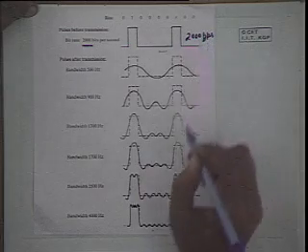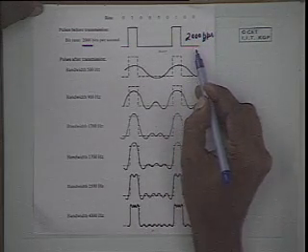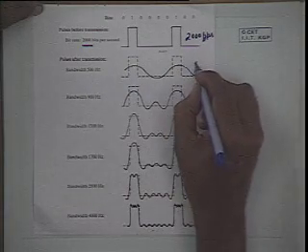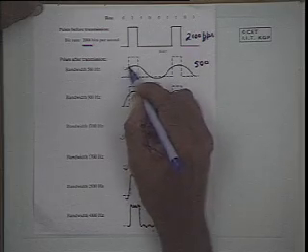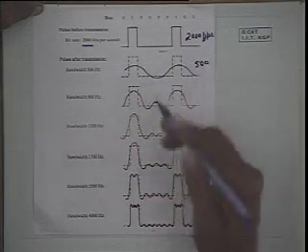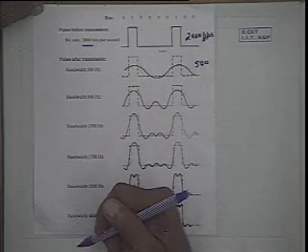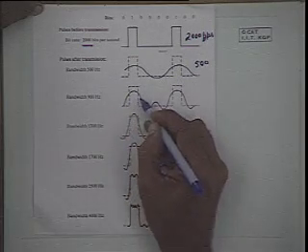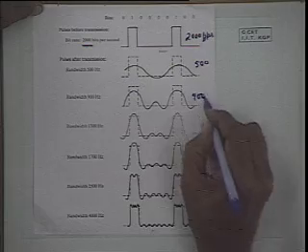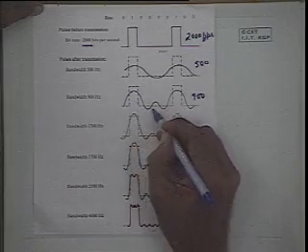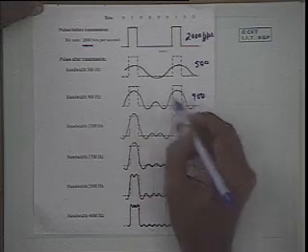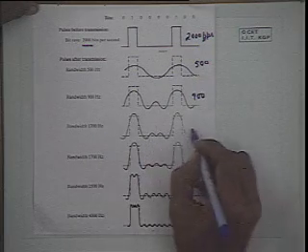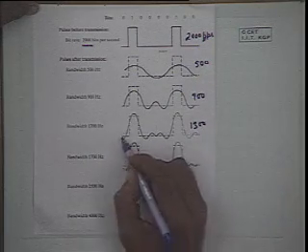And this signal, if it is sent over a transmission medium with bandwidth of 500 Hz, it will get converted into this form at the other end. On the other hand, if it is sent over a transmission medium with a bandwidth of 900 Hz, then it will look like this. This is somewhat better than the previous one. If it is sent over a medium with bandwidth of 1300 Hz, then it will look like this.